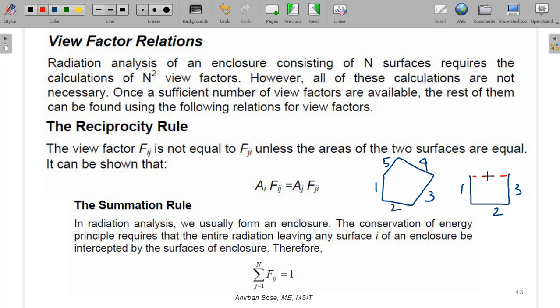We consider that it has temperature T infinity, and emissivity equal to 1, and we treat it in this way and find the view factors. Though for the view factors you do not need all these quantities, this is the way we find the view factors. So we consider the enclosure and then solve the problems.